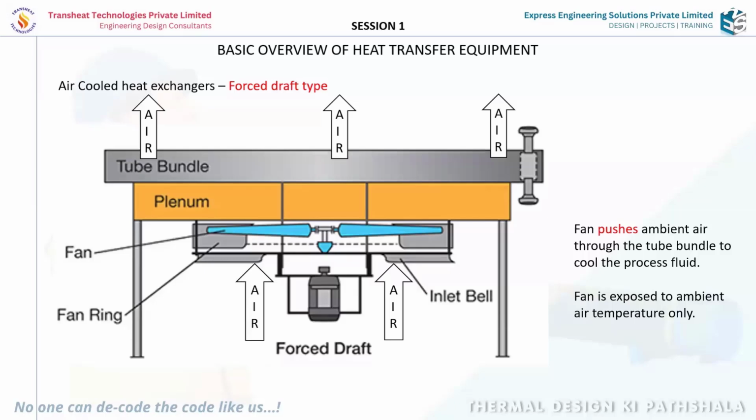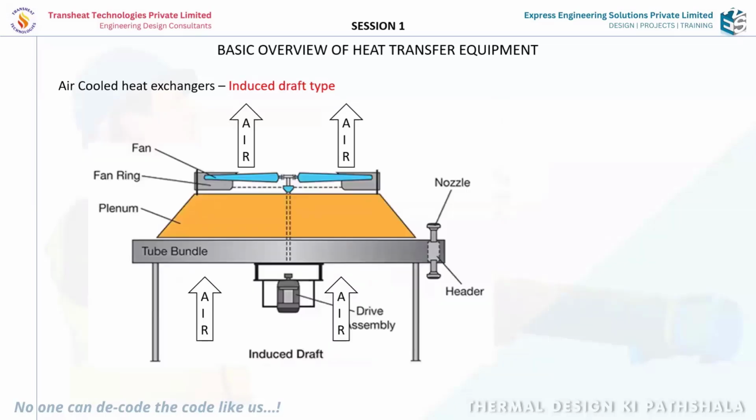As against this, in an induced draft unit, the fan is always mounted above the tube bundle. The fan is still sucking air, but it is sucking hot air now, because cold air from below the tube bundle is passing through the tube bundle, and the hot air from the top of the tube bundle is what is going to the fan suction. So the fan is always exposed to a higher temperature in the case of induced draft units.